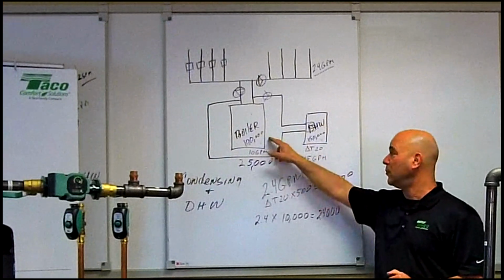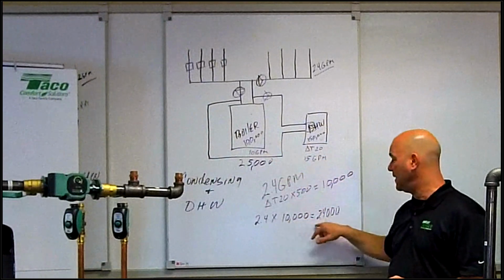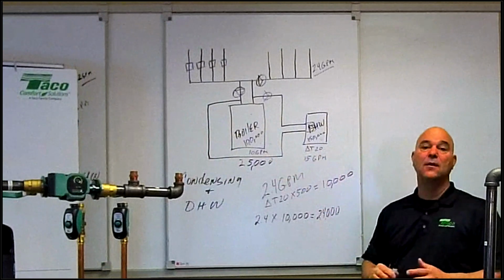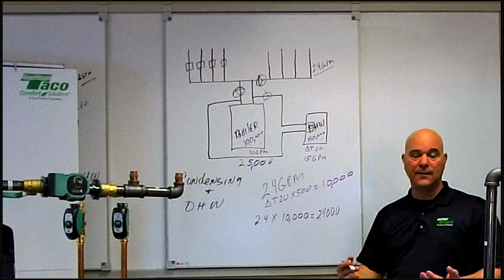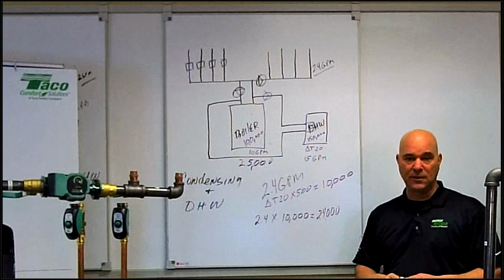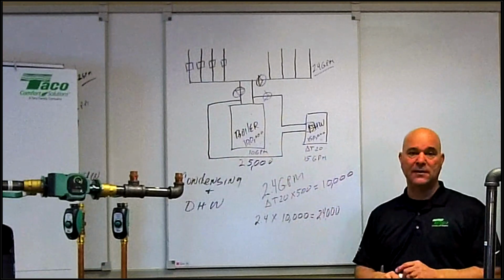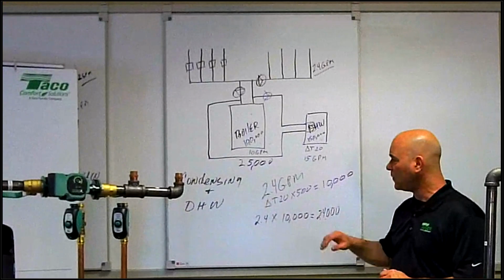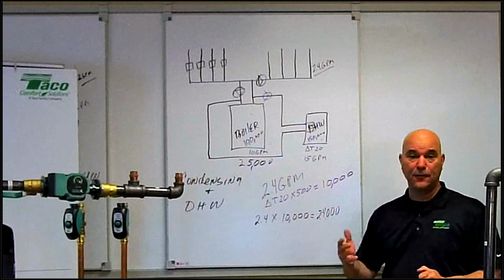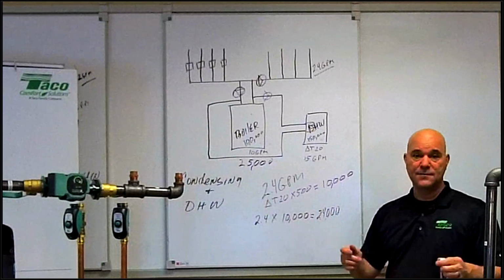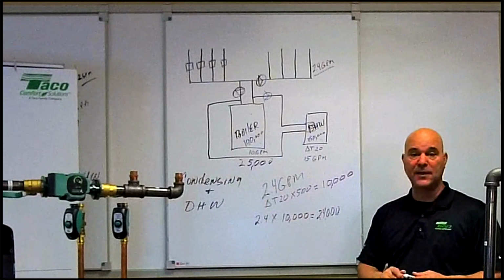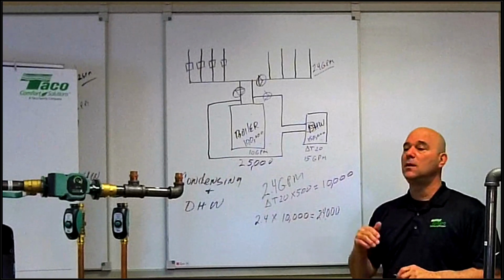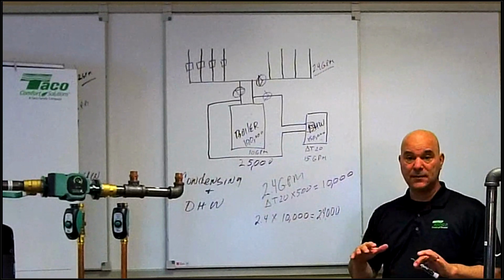Just make sure your boiler can turn down to the minimum load within the space, or we're going to create short cycling. We're going to have parts fail prematurely because of that. We're going to elevate the maintenance and operational cost of that piece of equipment. And we really want this boiler to live a full, comfortable life and supply the homeowner with the most comfort that we can. So that wraps up week 3.